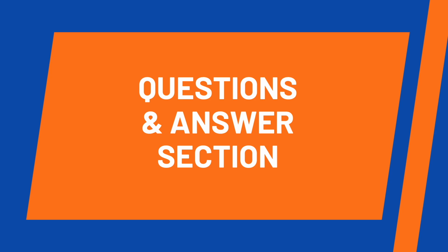So again, we had discussed, if you feel that your dust might be combustible, we always recommend doing a DHA. That DHA will point out very specific values. It'll point out recommendations of what type of protection you're going to need. Based on that DHA, we can then go into several different options for protection and mitigation devices. So is a mitigation system necessary? It depends on what the DHA comes back with. As far as what kind of isolation valve is needed, it depends. We typically go with a mechanical passive isolation valve in our applications.